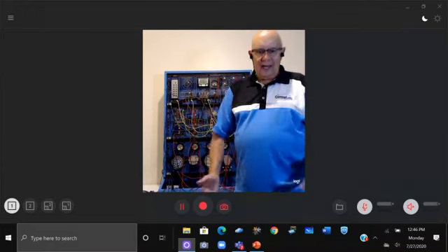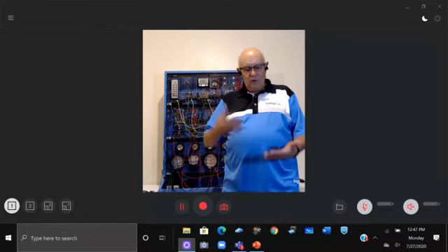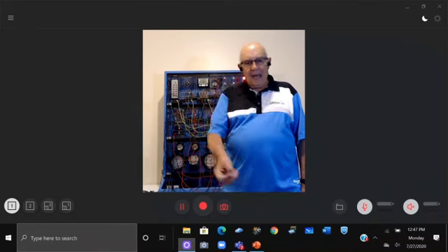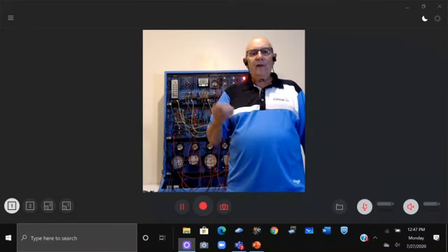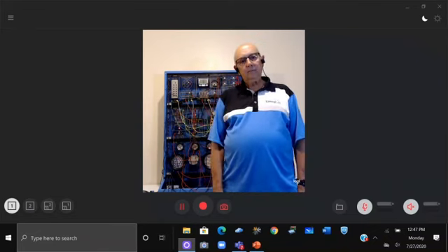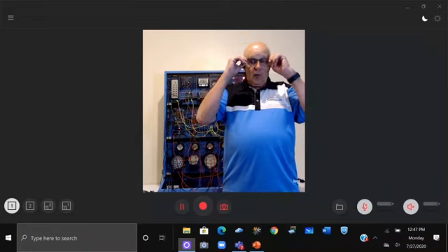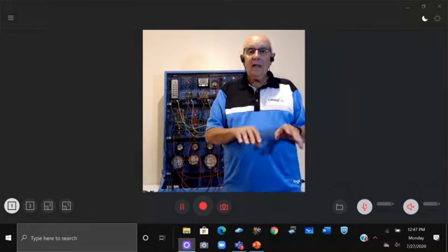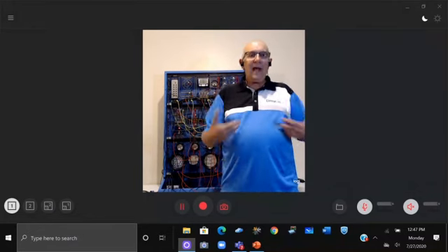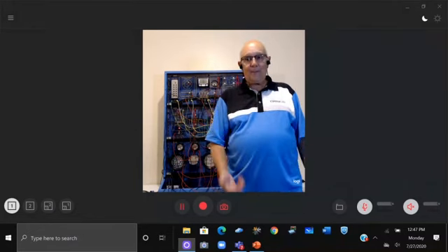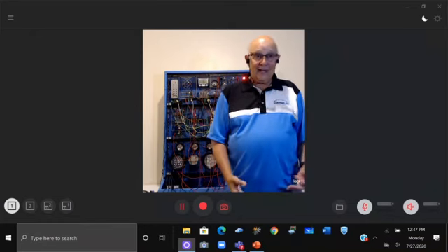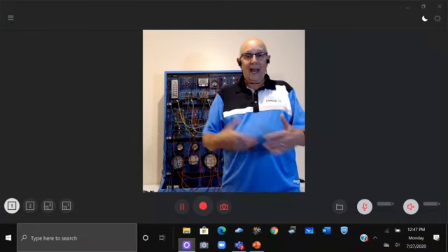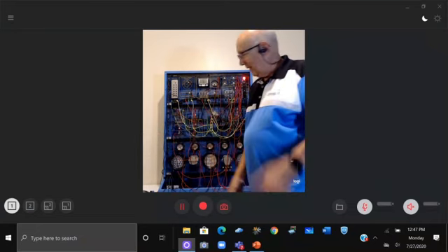Every chance you get, impress upon the student, do not connect or disconnect any module when the system is up, okay? Because you run the risk of causing damage. Not 100%, between you and me, it doesn't happen all the time. But if you're like me, guess what? It's going to happen, okay? It's going to happen in your class, it's going to happen to the principal's vehicle or the provost's or whatever. It's not going to happen to your car, Mike, anyway.